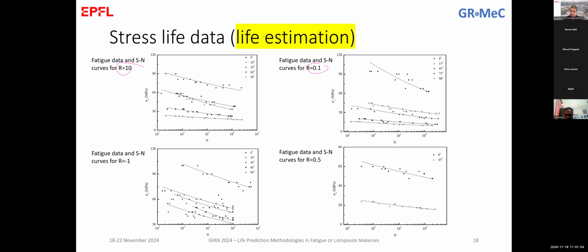So this is what might happen when we select 0. That's why we select a bit higher than 0 to have this kind of safety there, so that the machine, although it might do some overshoots in the loading, does not go from tension to compression. So this is technical details for the testing.